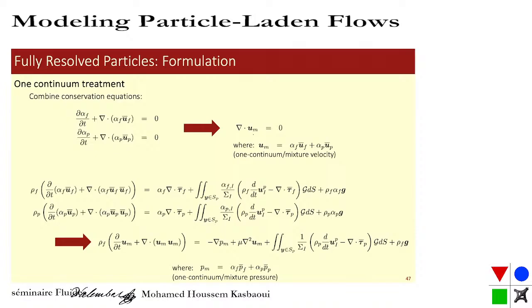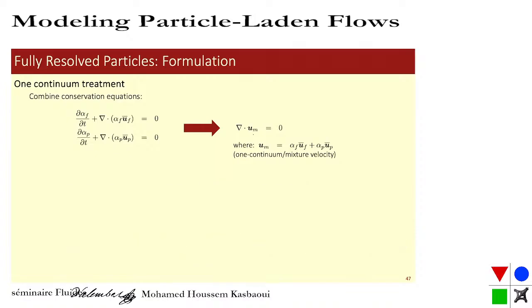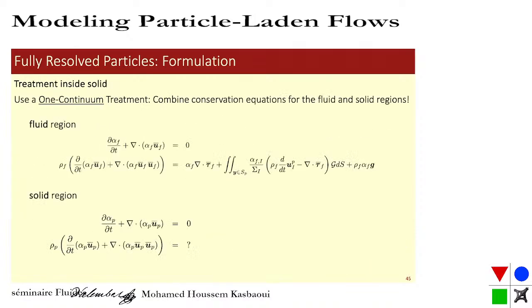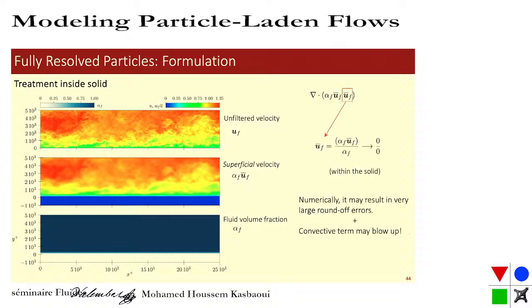So the second question was, and it's more of a philosophical question, if you have such a small void fraction, would using AMR type approaches be efficient? Yeah, that's also a good question. I don't think you're going to get away with AMR, because at the end of the day, you're going to have a cell where you're doing that 0 divided by 0.